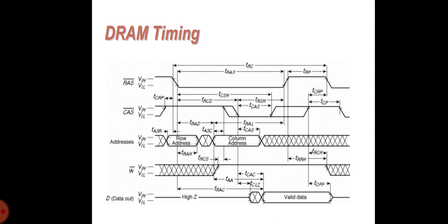Bringing these bits in and out of the memory chip can be accomplished with a high-speed synchronous interface operating at a speed close to the processor clock frequency. This comes at the penalty of extra latches and buffers at the interface into the memory core, as well as the high-speed circuitry to support the high data rate interface. The main contribution these memories offer is a redefinition of the interface into the memory. As long as data is written in large sequential blocks, this approach has proven to be very effective.